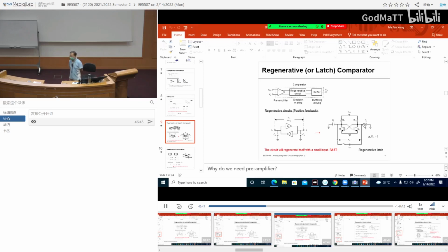So now what will happen to this circuit? Let's imagine. If this voltage goes up a bit, it means that M1 will get turned on more, which means that M1 will want to pull this output lower. Now, if this goes lower, that means M2 will want to turn off a bit more, which means that this voltage can go higher.